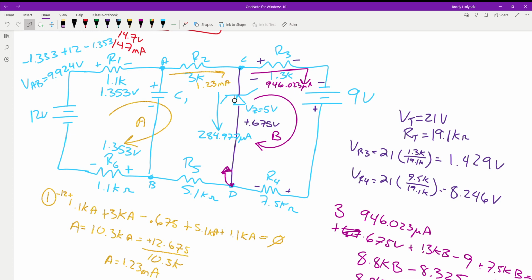Like I said, these ones are kind of fun because they make you think, but they're really not that hard. The biggest thing is just understand, what do I do with the capacitor? What do I do with the diode? The capacitor is the easiest part of the whole circuit. It's an open. The diode, we have to determine if it's forward or reverse bias, and then what is my voltage? So another way that would have been cool is if we would have upped this guy to, say, 15 volts. We would have had 0.7 here, and we would have seen the rest dropped across those resistors.